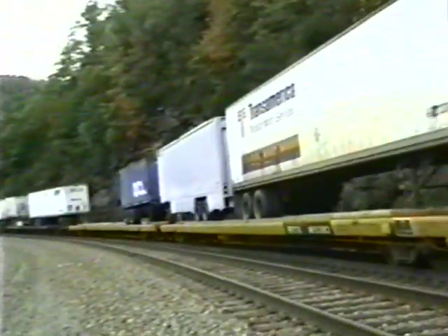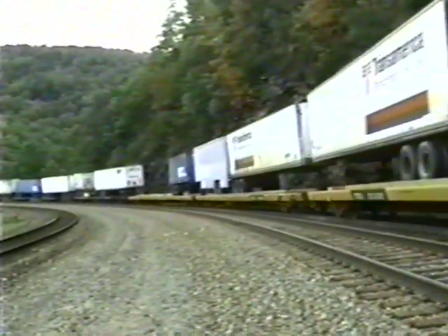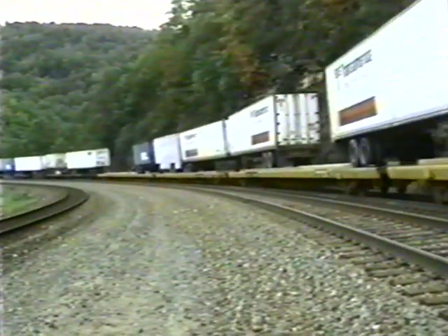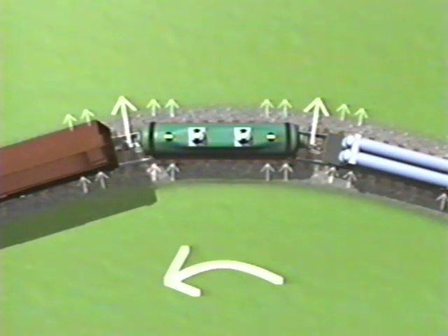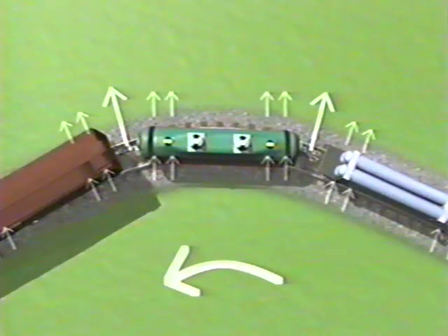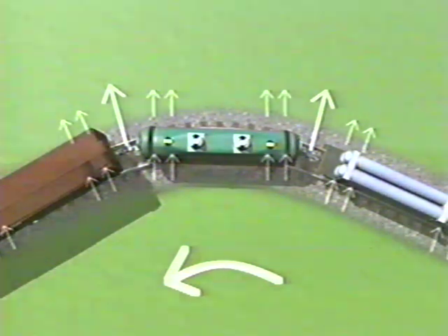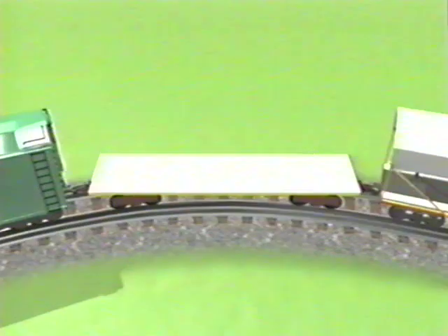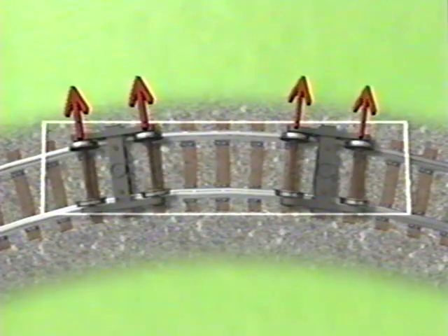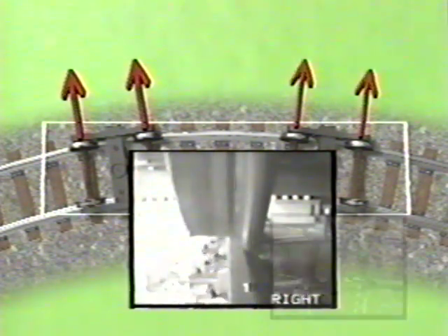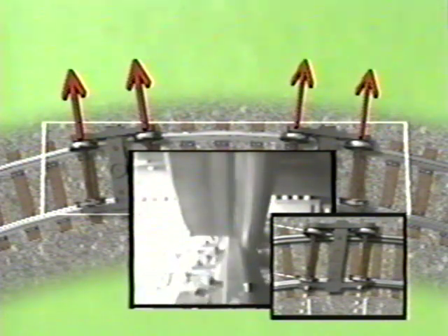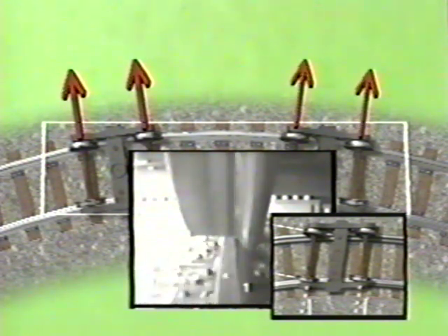Large lateral wheel loads can also be generated by in-train forces. Consider this train, which is in a heavy buff condition from braking in a curve. Large buff forces are transmitted from one coupler to the other in a train. The buff action generates a force in the lateral direction against the outer rail. The greater the coupler angle, the larger the lateral force. This force is reacted between the wheels and rails. The lateral force reaction may be large enough to cause the outer wheels to climb the rails, especially if the wheels are already at a large angle of attack to the rail.